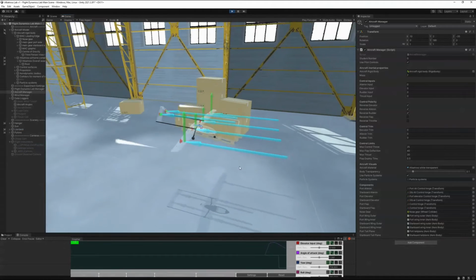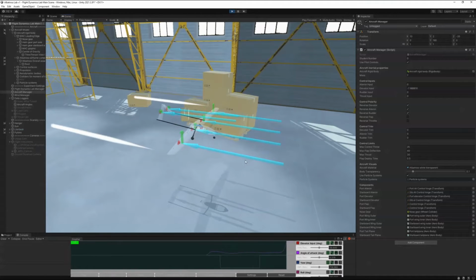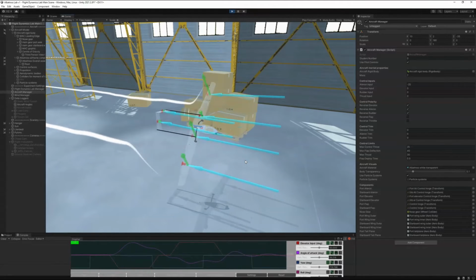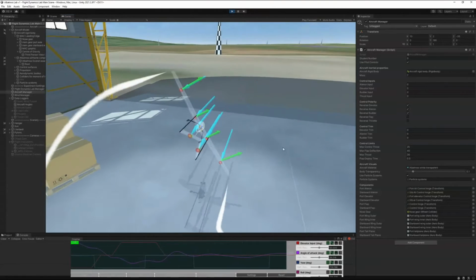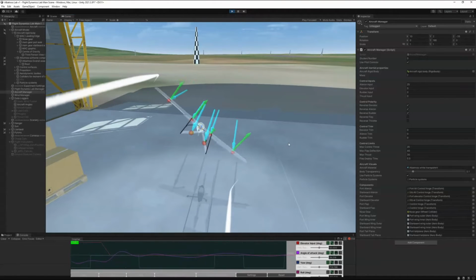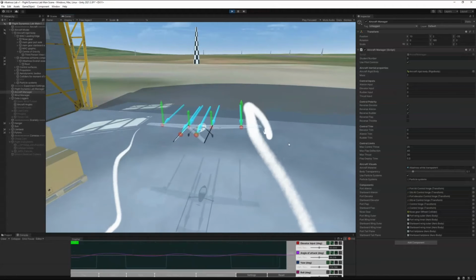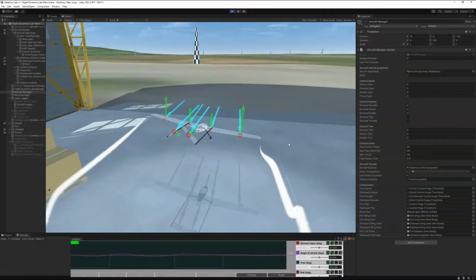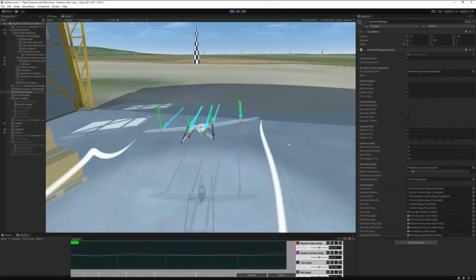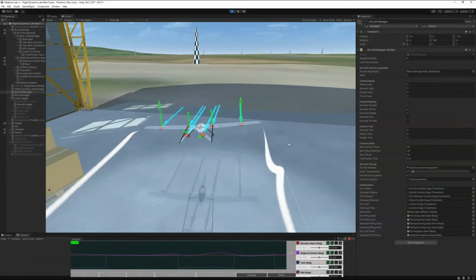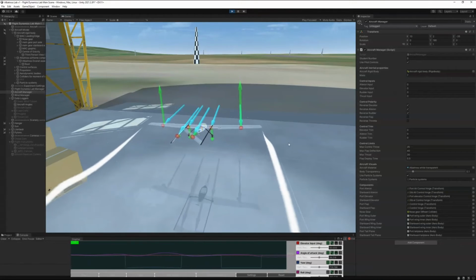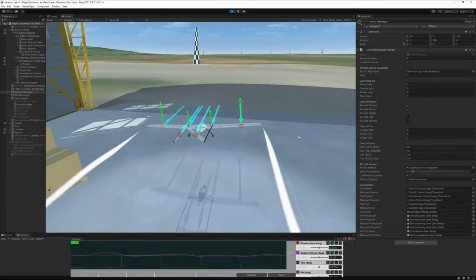Adjustment of flight control direction was needed so that the control of the Albatross followed a more intuitive input. This is done through changing control polarity settings on Unity, so that an up arrow input results in nose down, down arrow nose up, right arrow for a roll to the right, and left arrow resulting in a roll to the left. A and D keys control the rudder, left and right respectively. As seen, polarity for flap control was changed as deployment direction was initially the wrong way.